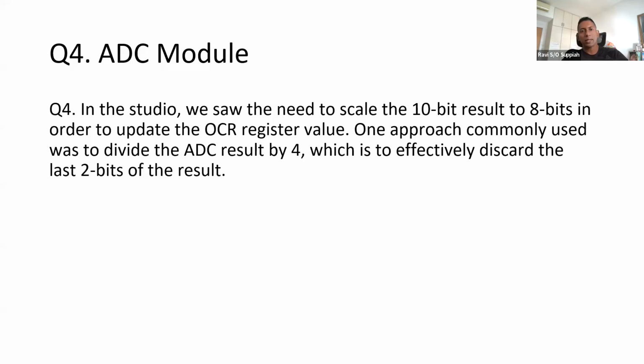Of course, when we have an analog voltage, before we digitize it, before we do ADC sampling, we need to do something else, which is the signal processing, correct? This one I will not go into. Those of you who have done EPP1 already know what we're talking about. That means things like filtering the signal, amplifying the signal, the gain using an op-amp, or things like that. You may want to do some first level processing of the signal to match the ADC input range.